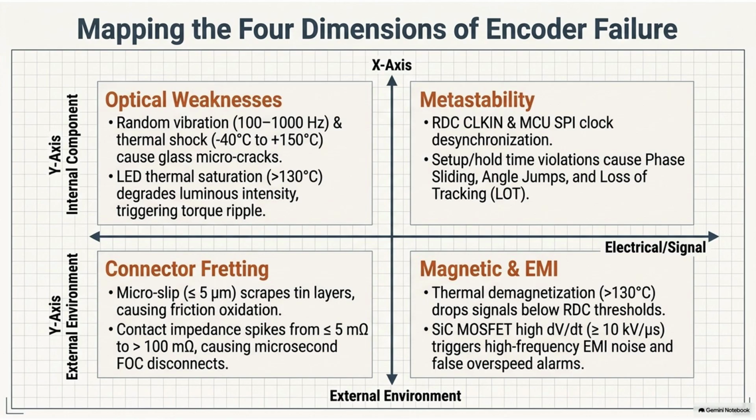And the critical failure happens at the transistor level, inside the digital registers. Yes. Every flip-flop circuit requires the incoming data to be stable for a specific amount of time before the clock triggers. That's the setup time. Right, and it must remain stable for a specific time after the trigger. The hold time. Exactly. So if the MCU clock triggers the register to read the data at the exact nanosecond the RDC chip is transitioning the voltage from a 0 to a 1, you violate that setup and hold time. The physical transistors in the flip-flop basically get caught halfway between their threshold voltages?